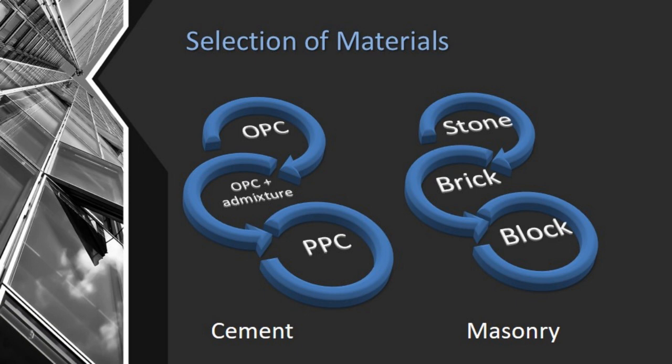So how the cement started, we have the whole literature behind it, but in industry we were actually using the ordinary Portland cement. Initially it was the 33 grade, then 43 and 53. The 33 grade just vanished. Then we worked on 43 grade and 53 grade OPC cement. As per the design and the requirement of the engineers, we choose the OPC cement. So ordinary Portland cement was the first step in this journey.